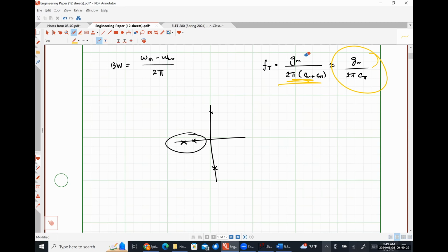I always get these backwards. The short circuit time constant approximation, which is used for low frequency, should give you a value that I think should be a little bit less. So it should underestimate where the mid-band begins, and the open circuit time constant approximation, whichever one is used for high frequency, should effectively overestimate where the high frequency begins.